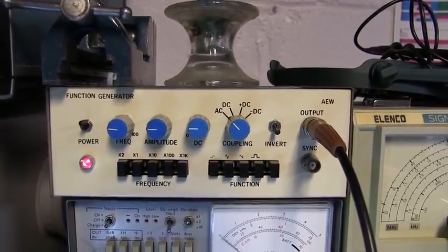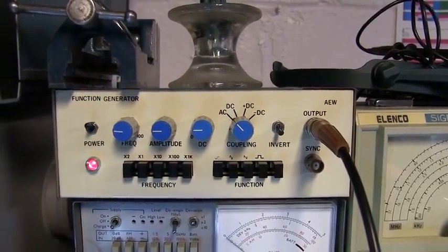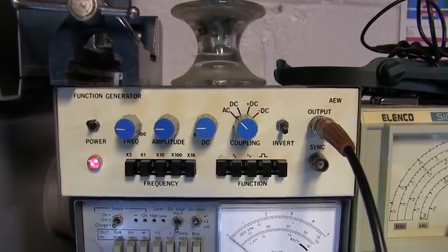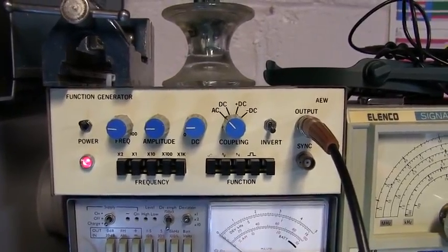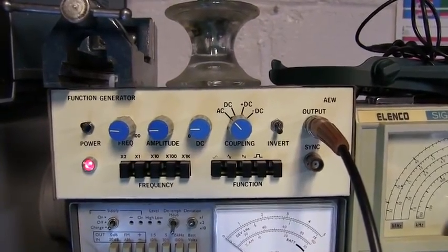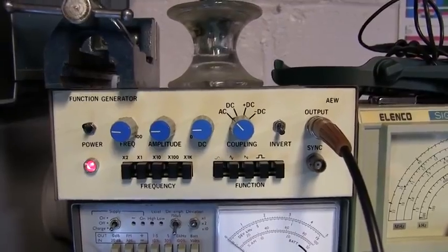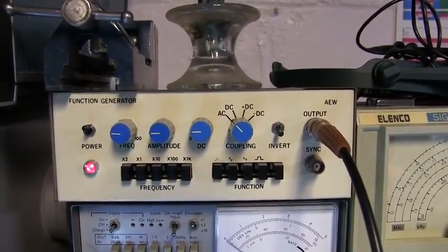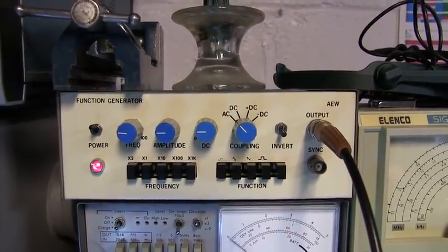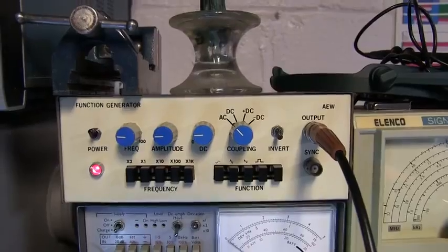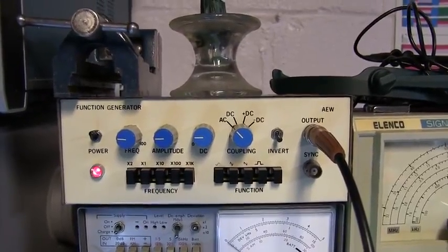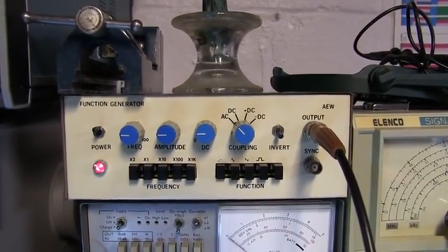Where if we used a square wave or a triangle wave, we're going to have harmonic energy that extends up to high frequencies. And the reflections that you get off the ends of improperly terminated cables might distract you from the actual results. So we're just going to use a sine wave at about 2 kilohertz, which will work just fine to characterize the output impedance of this device.